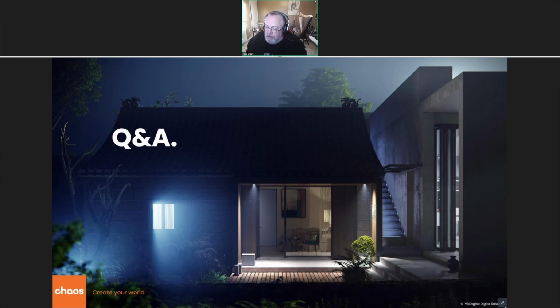Scatter, clipping is enabled. Does this affect reflections? Yes, and that's why with clipping there's the extend option. So clipping will narrow it to only what's in the camera view, and the example here is like a window reflecting some grass. You can extend that though, so that it cuts to the camera, but also a slightly wider area, so that you can still include things that will either cast a shadow into the scene from off camera, or would show up in reflections from off camera.